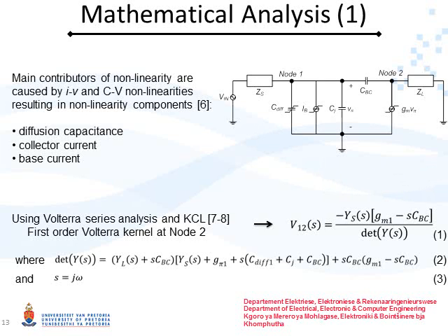The input signal in this figure is presumed to be small and therefore the nonlinear components are described as weakly nonlinear. To understand the behavior of these nonlinear components, Volterra series analysis is performed on the common emitter HBT model shown. The Volterra series is a powerful tool used for modeling and calculating the distortion components of weakly nonlinear systems with memory effects. Other simpler nonlinear models such as the Wiener, Hammerstein, and memory polynomial nonlinear models are also available. However, these models are variations of the Volterra series model and have limitations because of their simplified approach in characterizing the system.